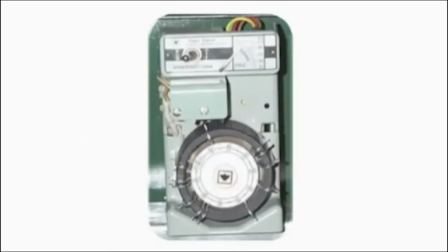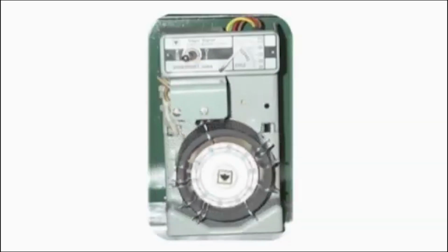The essential components are the dial that turns around once so often, which we call a cycle length. Then the dial has pins in it that trigger relays that give you the split, the green splits. Then you have one fixed point in the dial that you can reference an offset to.